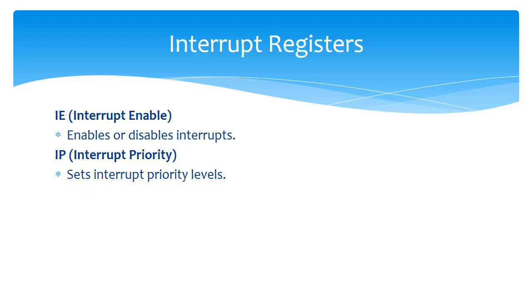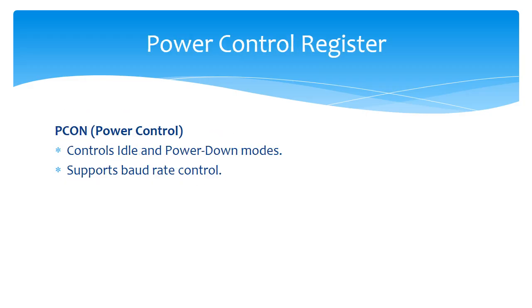So the next comes the registers for interrupts. This is very important. You have a number of interrupts. All these can be enabled only through the interrupt enable register, and similarly this register will enable and disable the interrupt. Similarly, the priority also can be set through the IP register. Making a bit 1 will increase the priority, whereas making the bit 0 will reduce the priority.